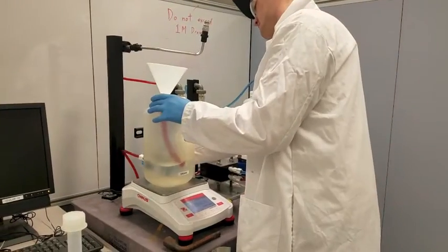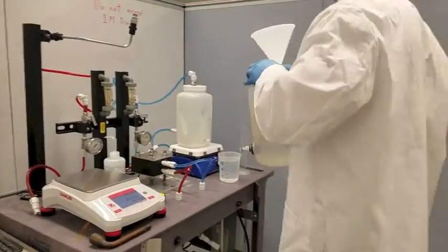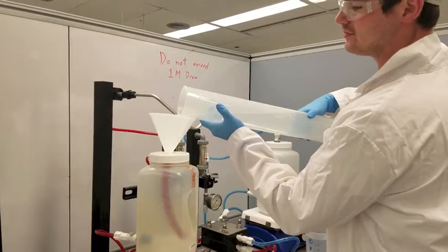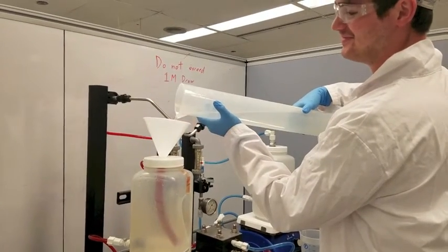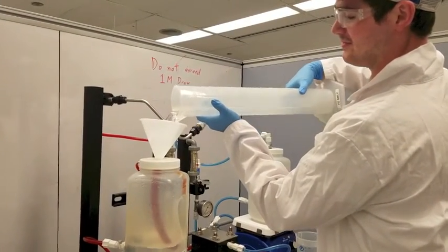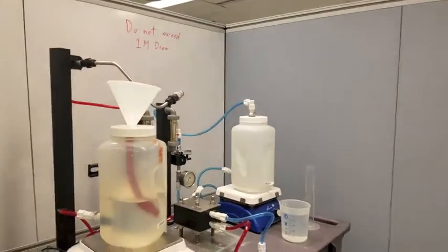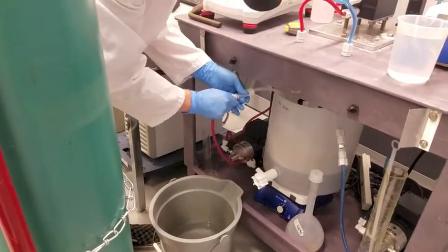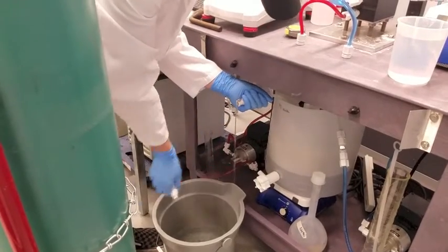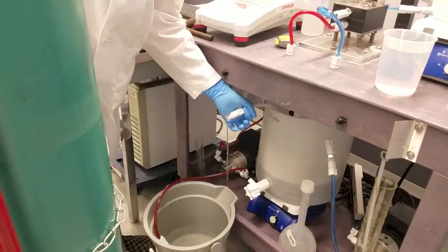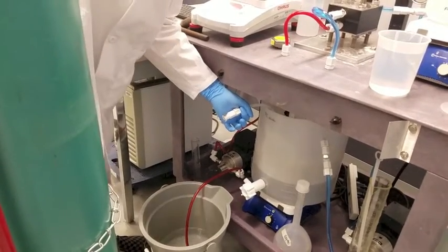Begin breaking down the experiment by emptying out the feed and draw tanks into a bucket, which you will then pour down the sink. Make sure not to throw away the stir bar. Then fill the system with DI water and run it for another 15 minutes. Once finished, you may then pour out the water. Now that the tanks are empty, you may begin air purging the system. Turn on the pumps, making sure that flow rates have been given enough time to level out.